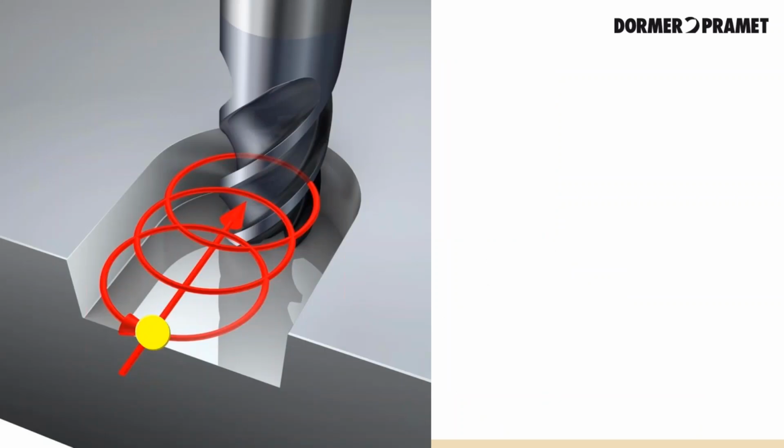The first is trochoidal milling. Trochoidal milling is an ideal process for applications such as scallops and narrow wide grooves. Trochoidal milling is a 2D method using high-speed milling techniques in a confined space or slot in tough materials such as hardened steel, stainless steel, and heat-resistant superalloys such as Inconel.